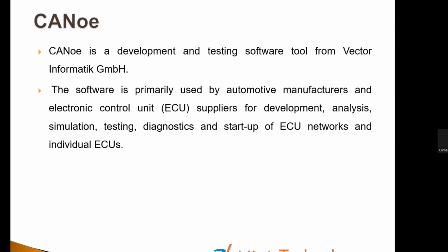I connect 2 or 3 instrument clusters to CANoe and make it run for weeks. It will do 1 lakh times or 1 million times as per the customer specification, and then it will complete and give you the results. That's one typical example where you can use the CANoe tool in testing.